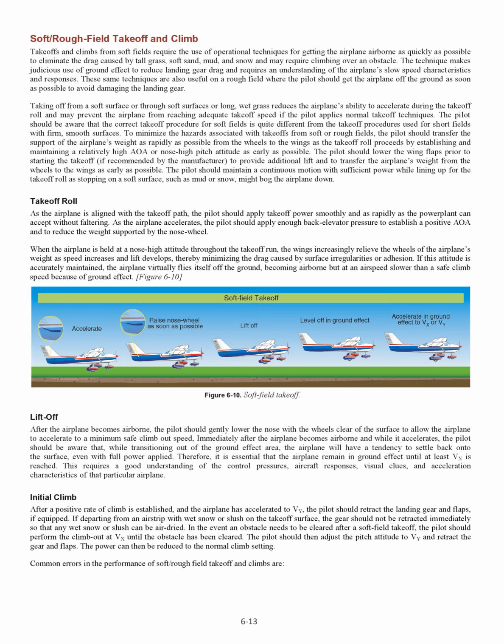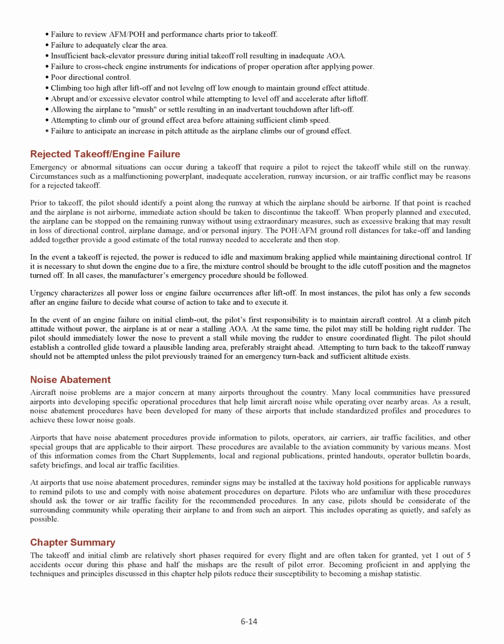Common errors in the performance of soft/rough field takeoff and climbs are: failure to review AFM/POH and performance charts prior to takeoff, failure to adequately clear the area, insufficient back elevator pressure during initial takeoff roll resulting in an inadequate AOA, failure to cross-check engine instruments for indications of proper operation after applying power, poor directional control, climbing too high after liftoff and not leveled off low enough to maintain ground effect attitude,